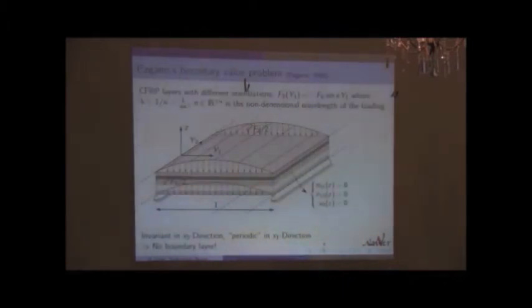Okay? So this is a kind of inevitable exercise in the laminated composites community. You must compare with the exact solution derived by Pagano in the 70s, almost 70s, for the cylindrical bending of laminated plate. It's almost an academic exercise now. So Pagano derived an exact solution for the bending of laminates with the following boundary conditions.